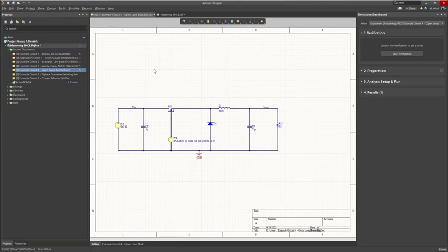And for this buck converter, I didn't really do the calculations from scratch. I just did some rough calculations and chose some capacitor values. But with simulation, the good thing is that I can see what the performance is going to be like with these values and this pulse frequency.